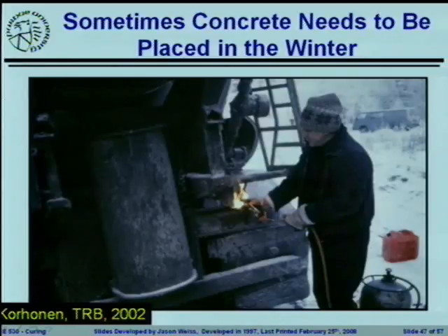One, obviously freezing water is going to make it very difficult for that cement and water to react and undergo the hydration reaction. The other thing is a real practical issue here, and as I mentioned before, this driver is going to go up and down on this truck several times. And he's spraying off the back of the truck with water. That water is hitting the back of the truck. Water, when it undergoes that phase change to become ice, becomes slippery.